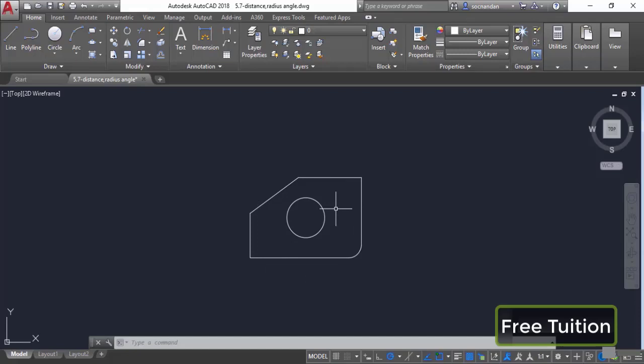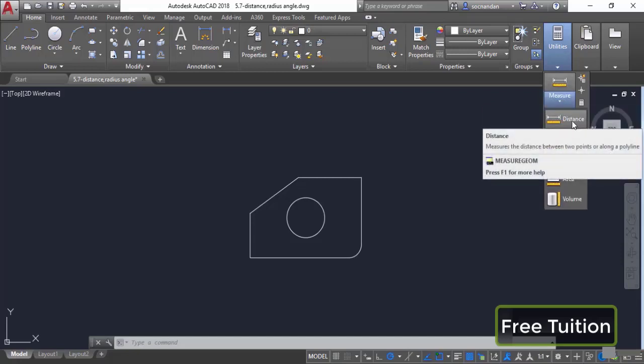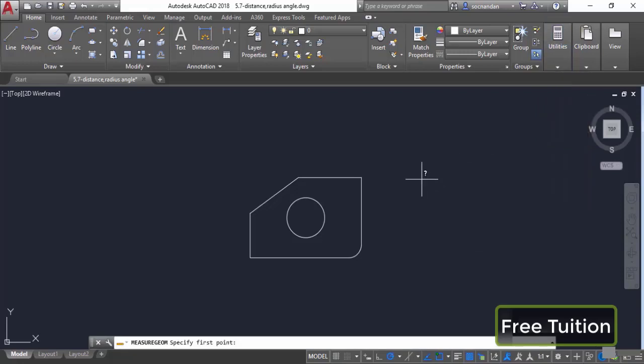The inquiry commands are simply the commands which can be used to find these values, and you can find those commands here on the utilities panel. So go to this utilities panel, and here you will see this flyout. From this flyout select the distance option first. You can also start this distance tool from the DI command.